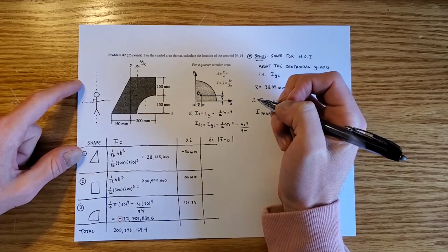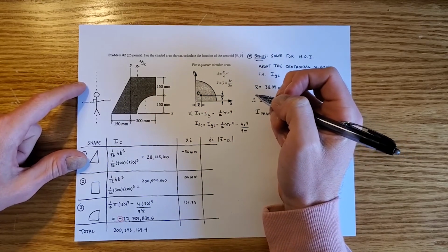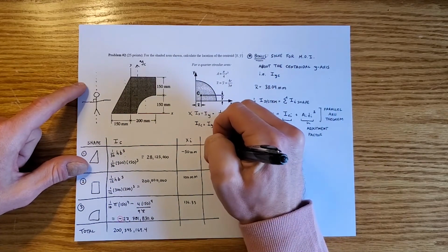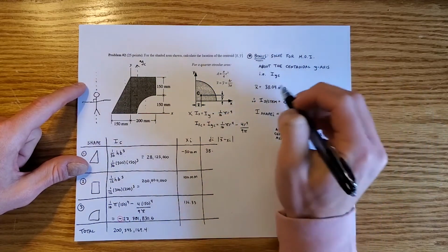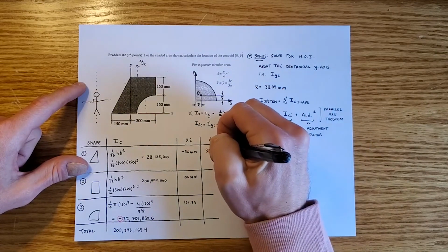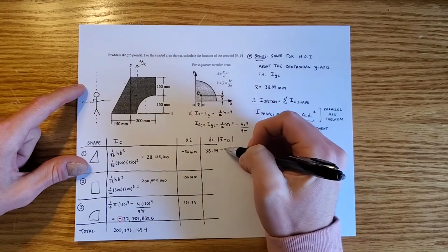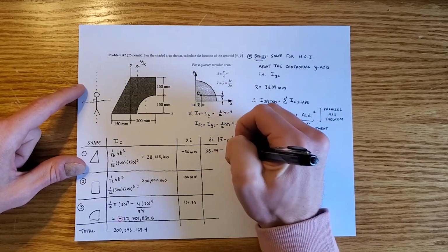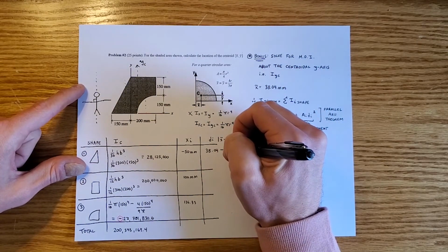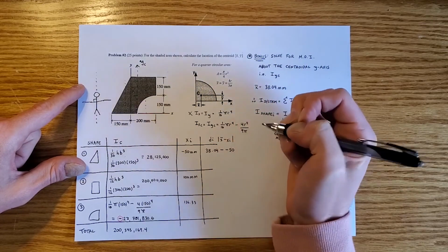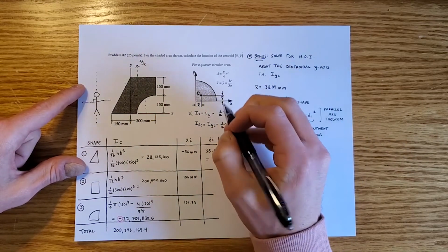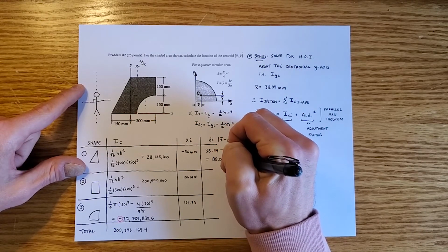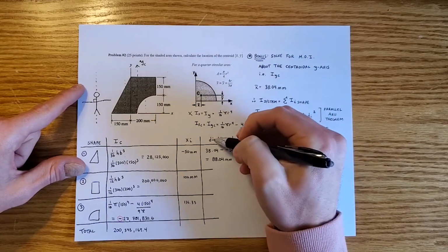So in this particular case, the x bar is the x bar of our shape. So for this particular case, we have 38.04 from before, minus the xi. Well, what was the xi over here? Well, it was negative 50. So we have 38.04 minus negative 50. So this actually gets us a value here that the di is 88.04 millimeters. But what is this di referring to?